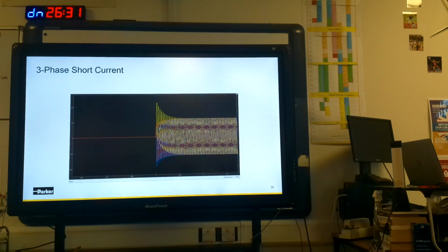But that braking torque would be the same in a low value right up until the point that you're getting to be at very low speed, and then it will maximize to something quite big. So in that scenario, you'd be slowing down, and all of a sudden, just before you get to 0 speed, you'll come to a juddering halt. Again, not particularly wonderful. If you had the ability to know what the speed was and be able to go from a three-phase short circuit to a 6 switches off at a low enough speed, you could avoid that problem.